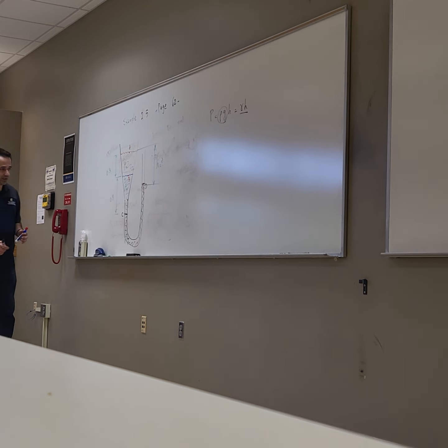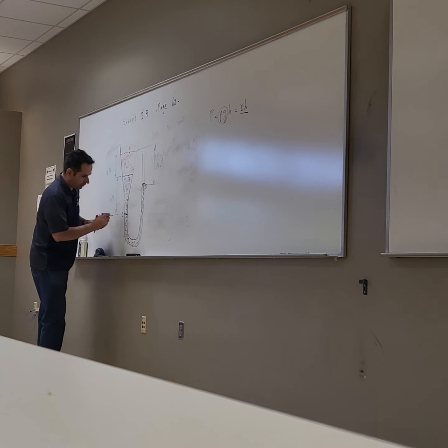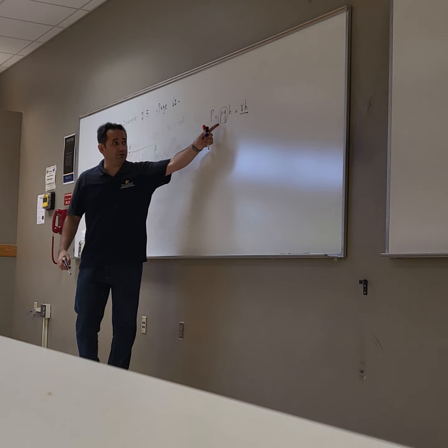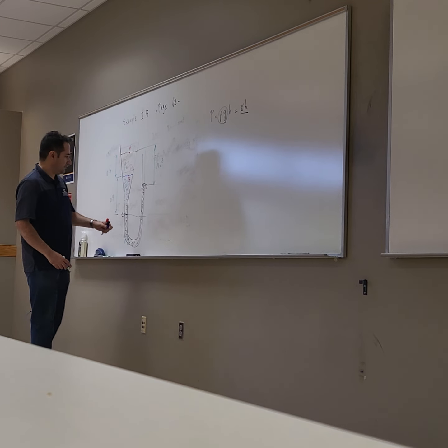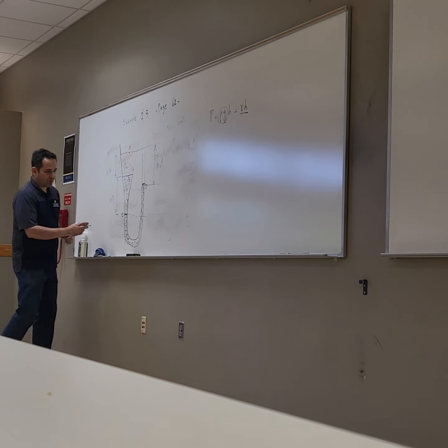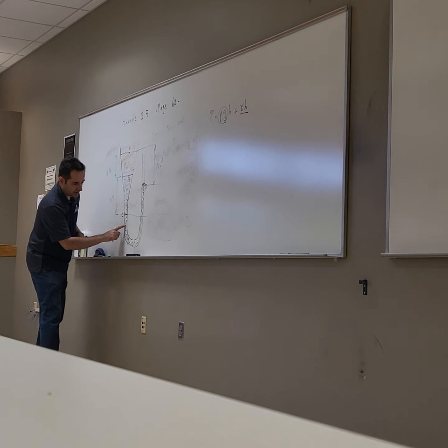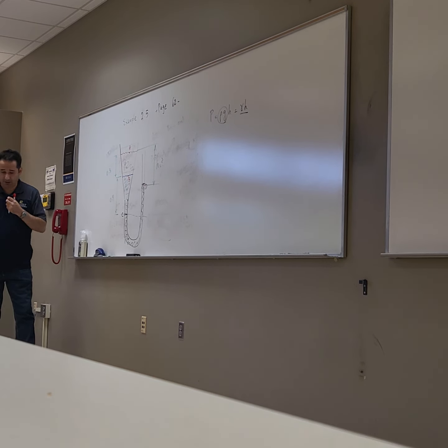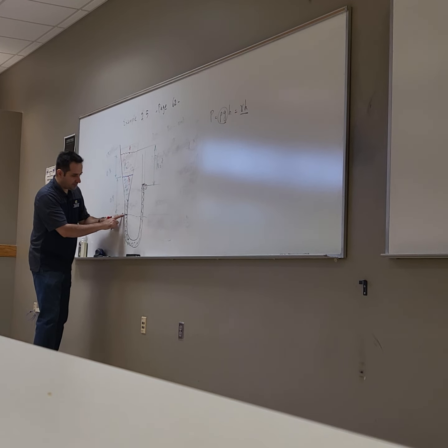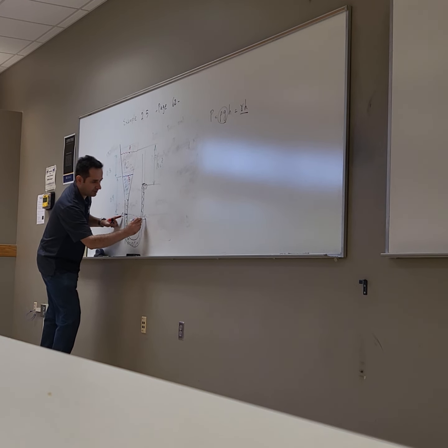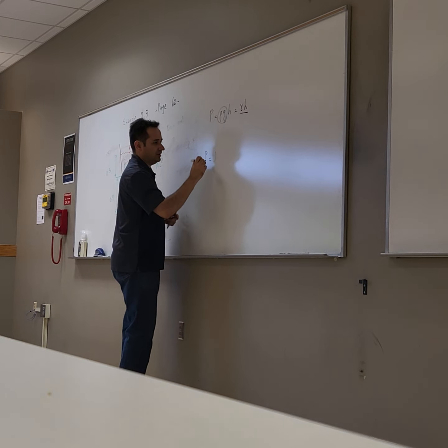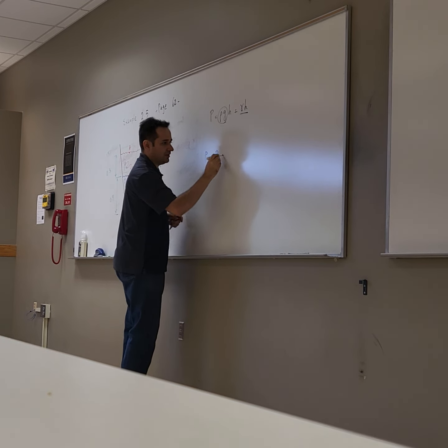So here is what I can do. One way is to look at this point C, right? According to that formula, the pressure only depends on the height and the density of the column of fluid. Because C is in mercury at both parts of this U-shaped tube, call this point C prime, I can say P at C is equal to P at C prime.